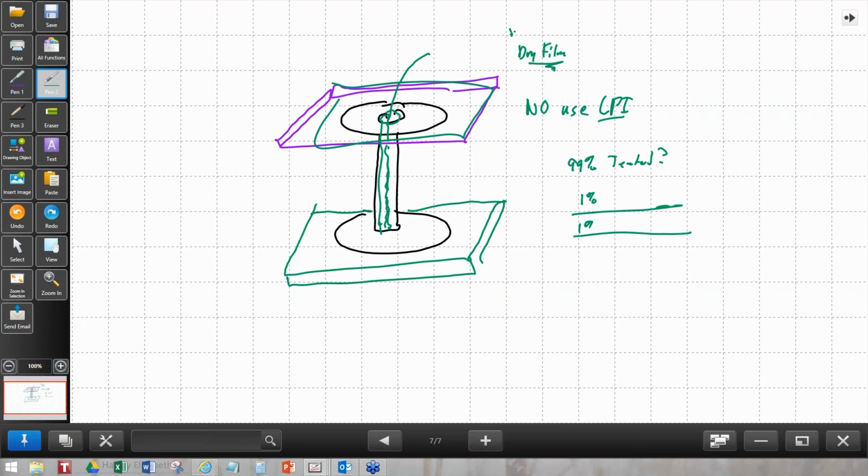And 1% of the time the bottom could be open, which means about 2% of the time it could be open on one end only. Hence if you get any crud inside, which is typical from soldering and post assembly cleaning operations, you'll get it in the hole. You'll end up with moisture. It will be a problem. You don't want to do that.